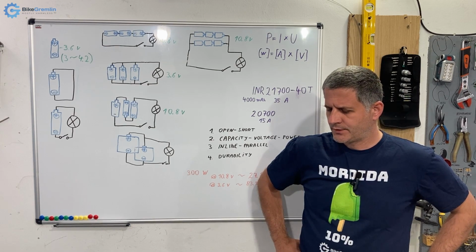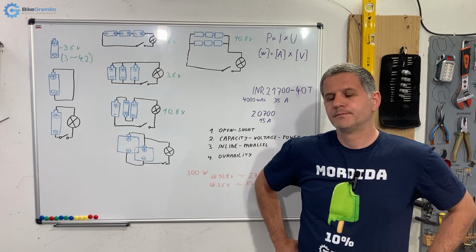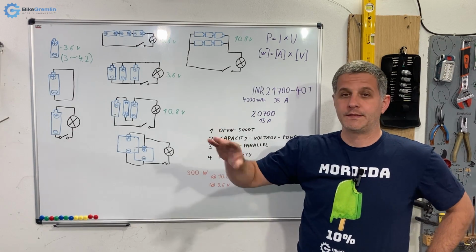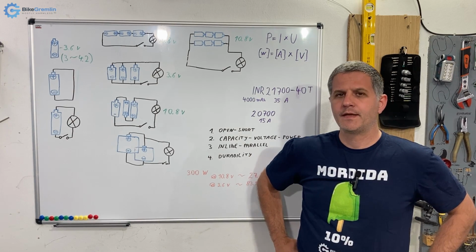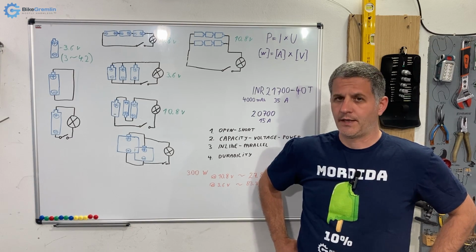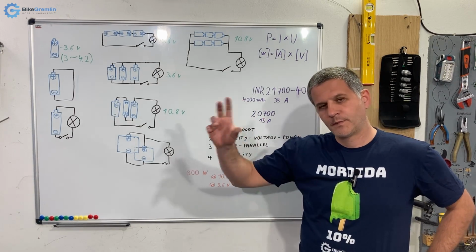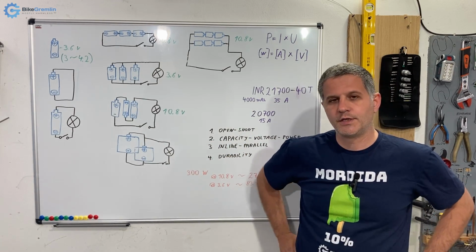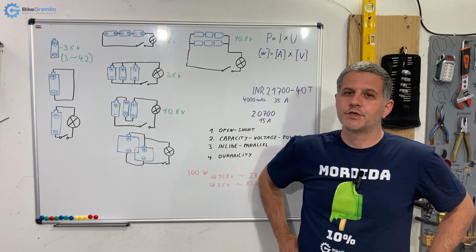Another thing is about fast chargers. All the NiMH batteries, for example, they liked being charged to full capacity, so that's a difference, and they like being charged with 1/10 of their capacity, so to charge them properly it would take about 10 hours. With lithium-ion batteries and other similar modern technologies, lithium iron phosphate and so on, that's not really the case, not in such an extreme way.